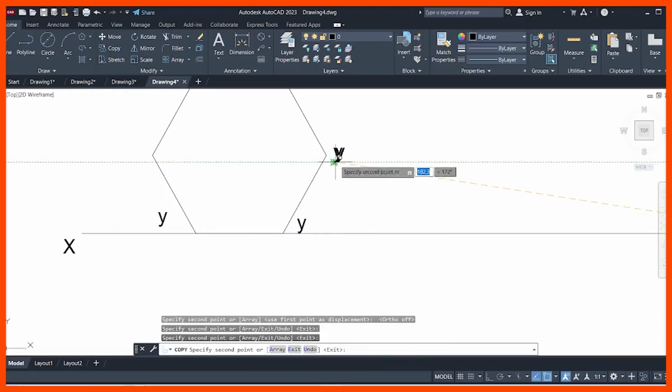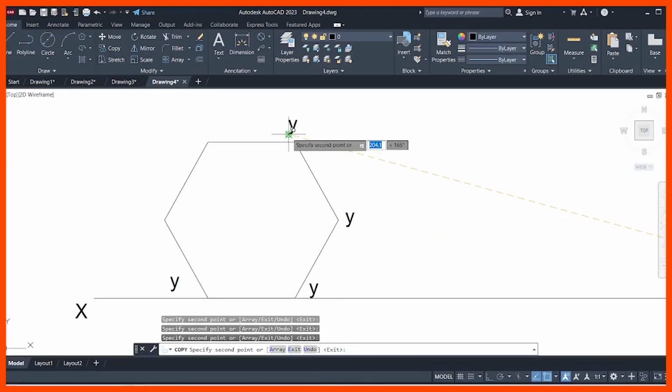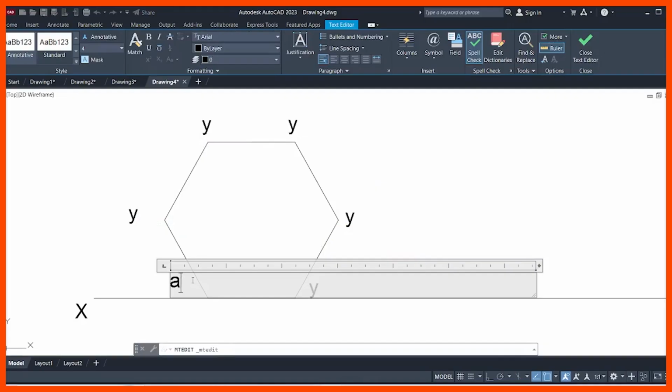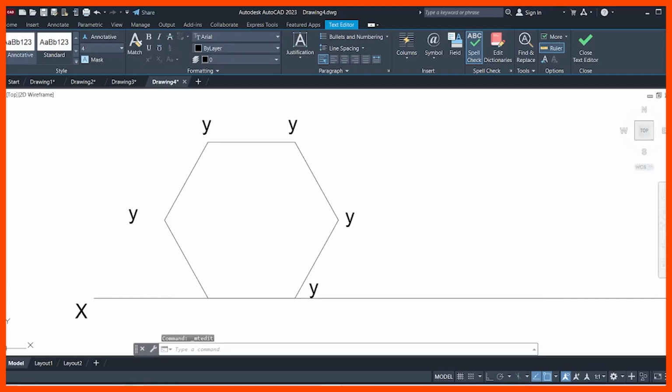B, C, D, E, again F. So here this is A dash and in bracket 1 dash. So why are we taking 1, 2, 3, 4, 5? This is the back side of the hexagonal plane. There are 2 hexagonal planes in the prism, the front portion and the back portion of the hexagonal prism. The back portion of the plane is not visible. Those marking points are not visible. That's why those points are put in the bracket.